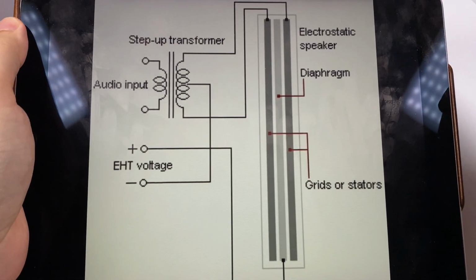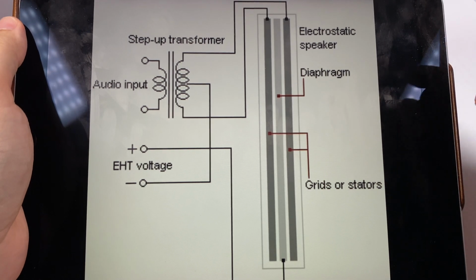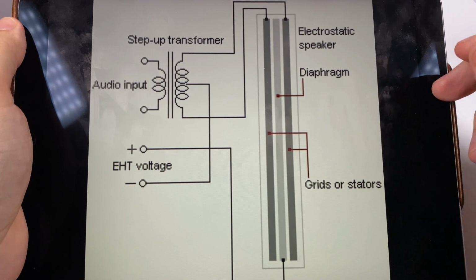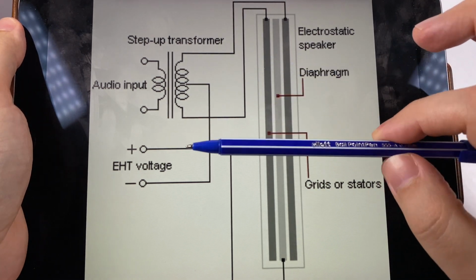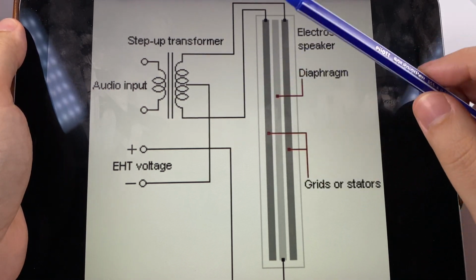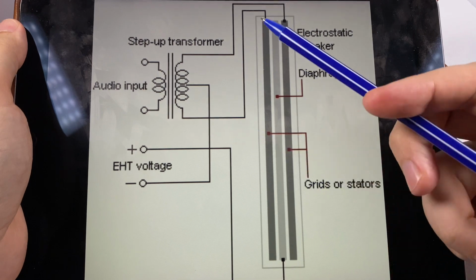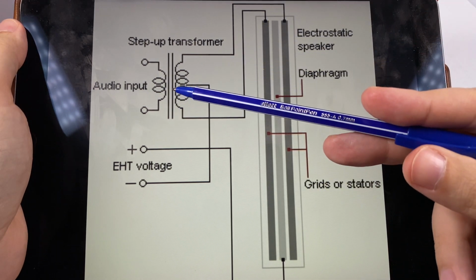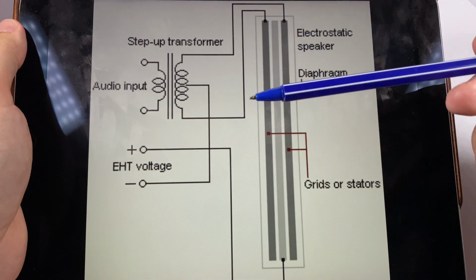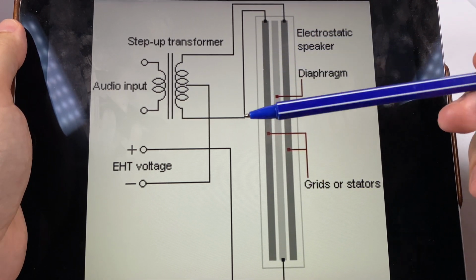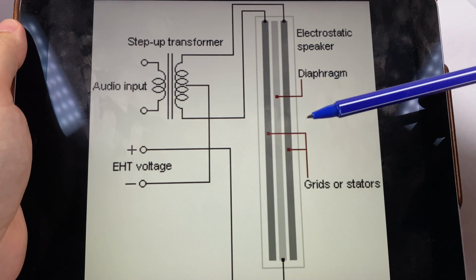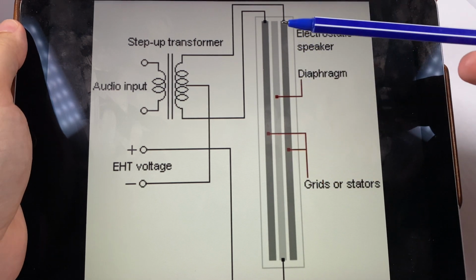for low frequencies, sometimes it's hard to achieve a good amount of bass, because it's sounding super fast and super resolving, and because of that sounding dry. And also this schema requires an expensive amplifier with a step-up transformer, or just an amplifier that produces really high voltage. Also, first models of such speakers were pretty hazardous because of the high voltage used there.